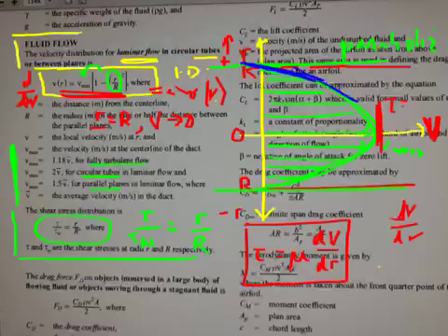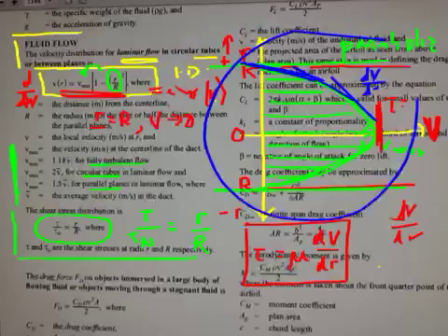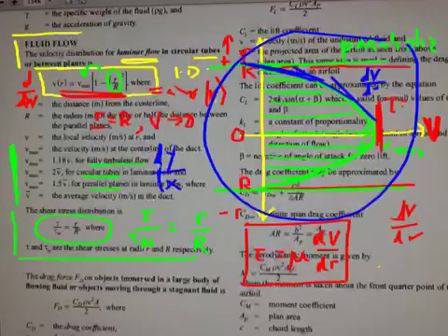So it's just the slope of this curve, the slope again being dv dr. So kind of rotating this whole thing: normally we're used to saying dy dx, and this is kind of on its side. So all this equation is saying is that the maximum shear stress you'll get is at the wall, you'll get the minimum at the center, and in between it's just proportional to the value of r over R.